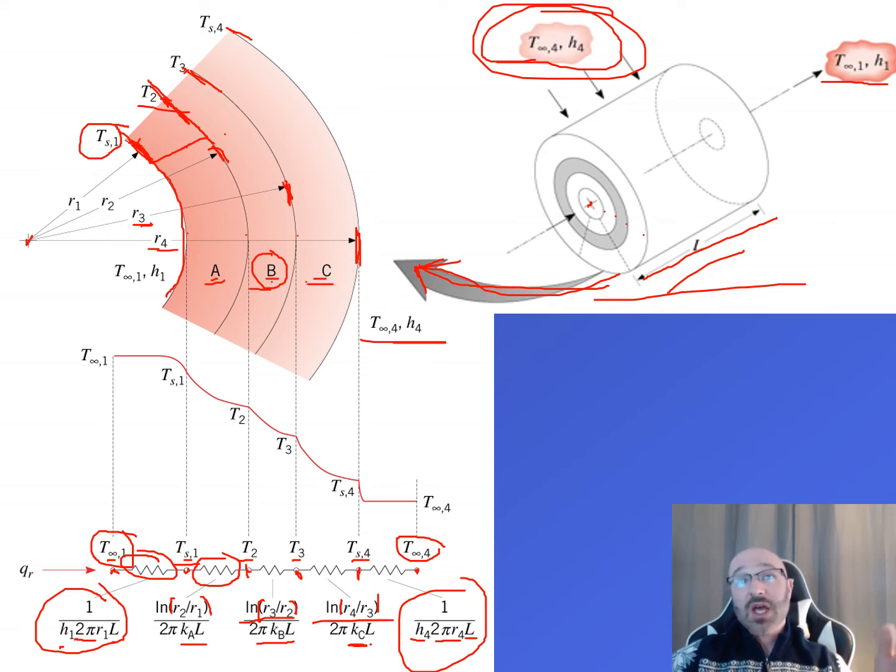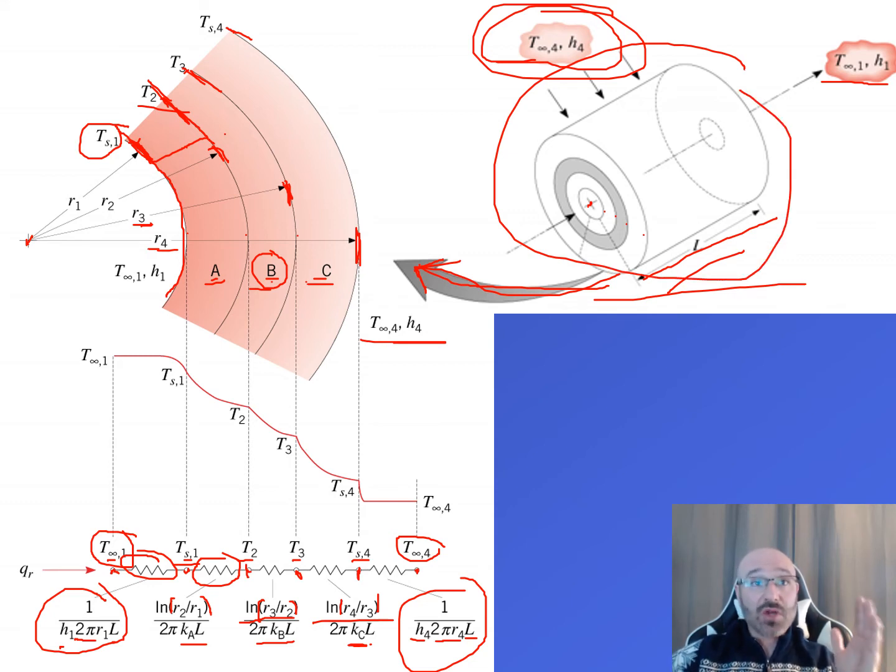So we can see it's really important to go from this initial 3D diagram, draw out a 2D representation, and make it nice and big so you can clearly understand everything that's going on: your fluid temperatures, where conduction occurs, where convection occurs. From that, directly below it, use your lines, draw out that thermal circuit, drop the node straight down, and ask yourself at each step, between this surface and this surface, what's going on? Okay, this is my governing equation, and plug it in.